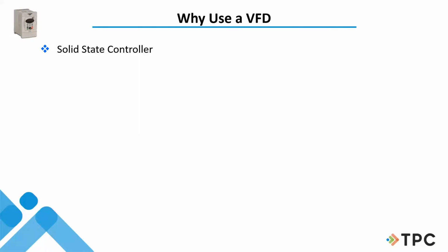We also get rid of the overload block, so we don't have those heaters that we would typically replace, or they burn up once in a while on us, and the contacts that are in the relay block fail occasionally. So there's quite a few things that the VFD really helps us get rid of some old technology. Not that it's bad technology, but we have some things that are a lot better, and solid state control is one of them, and they've come a long way in the last 30, 40 years. So not necessarily bad, but solid state's a good thing to replace a lot of that old equipment.